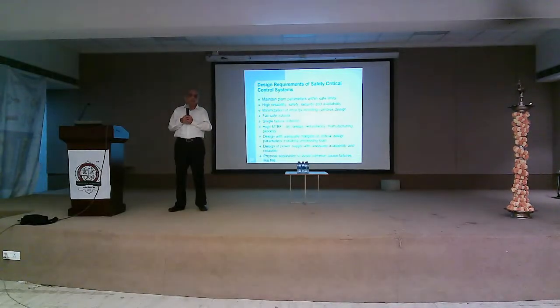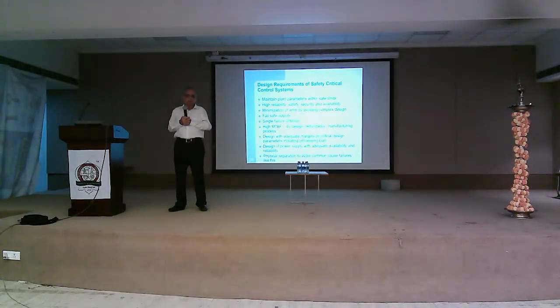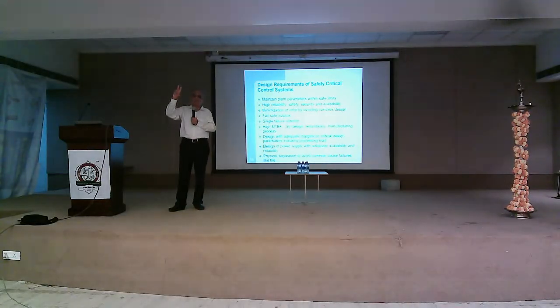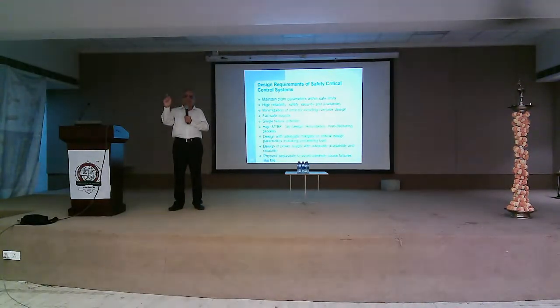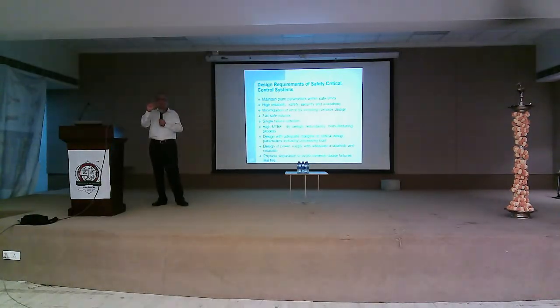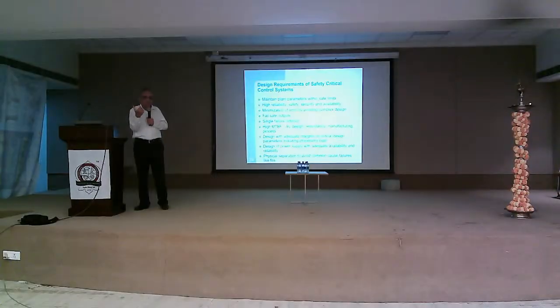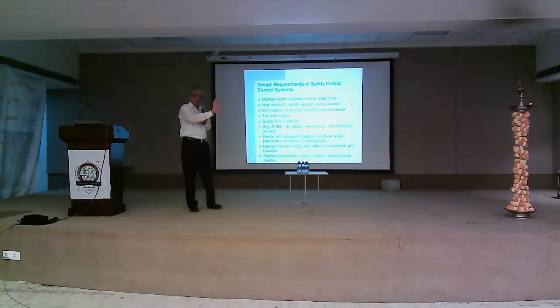If my system needs 5 volt 10 ampere, I will not operate at 10 ampere. I use two 5 volt 10 ampere power supplies connected through Schottky diodes to the load, so that each supply will carry 5 ampere. Even if one power supply fails, the other is still working. But this is one system.